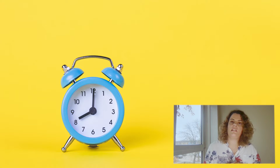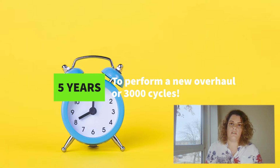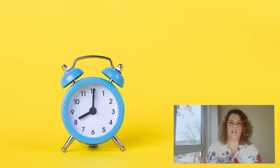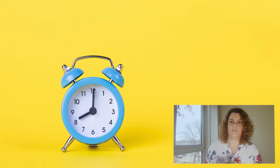So my question for you is, how long do you think it takes to do an overhaul on average, and for an average aircraft engine? Well, it takes about 5 years or 3,000 flight cycles. So whenever one of these limits is reached, then you perform an overhaul. It can also happen that an overhaul is performed if the maintenance engineers find something in the monitors that tells you that something is not going correctly. And then they can request an overhaul sooner.